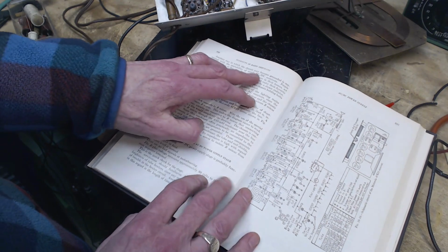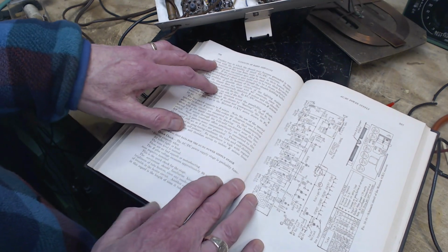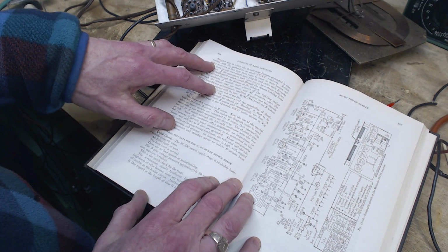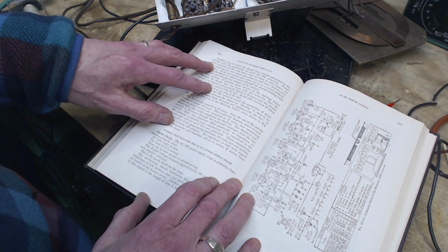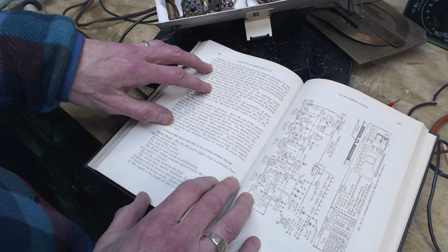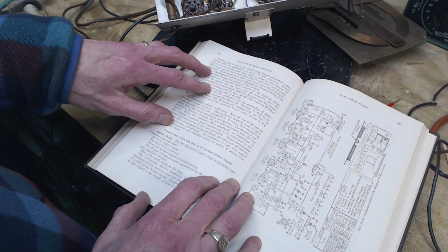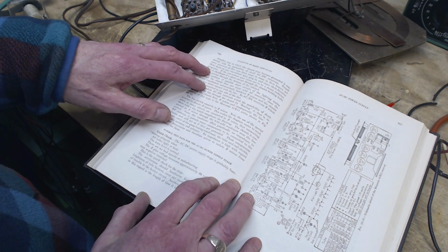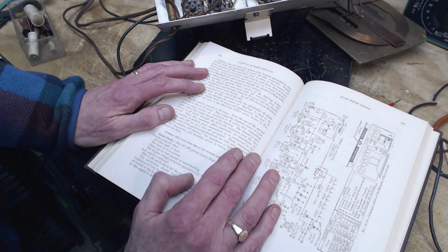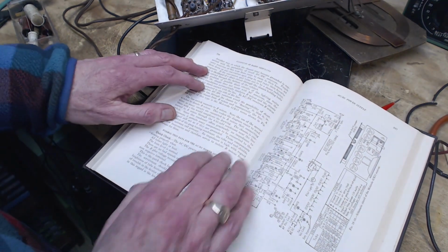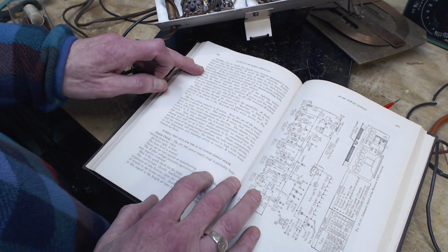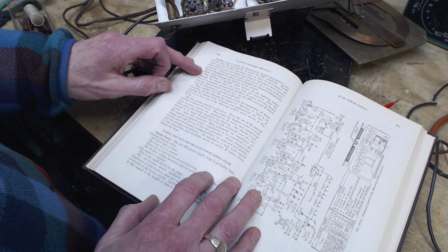Another way in which the chassis may become grounded is connected with the portability of small AC/DC receivers. People carry receivers of this type from room to room in their homes and set them down in any convenient spot, plug in, and enjoy their favorite programs. If the convenient spot turns out to be a steam radiator, that's good. I guess in the summer you could put it on your steam radiator. There is a likelihood of a short circuit through the chassis holding bolts, which extend through the bottom of the